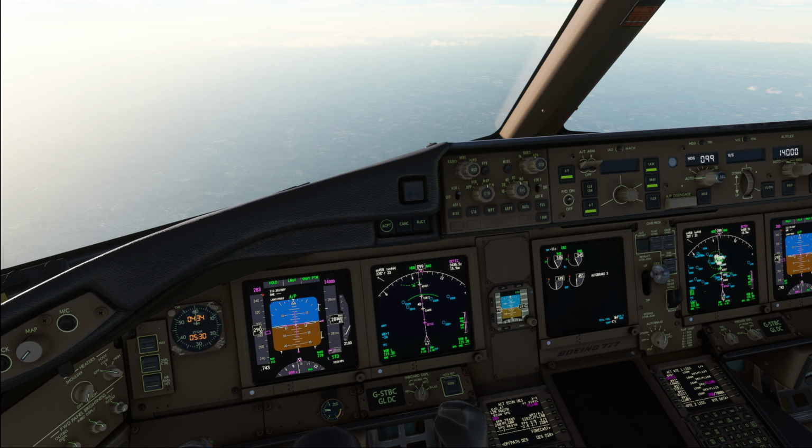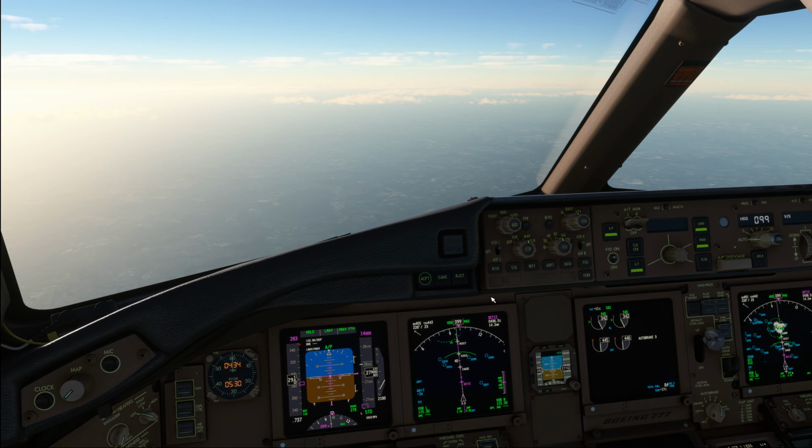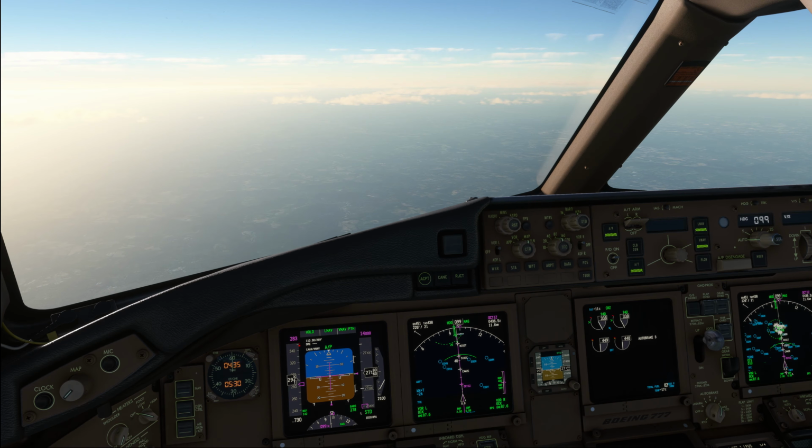To give you an idea of what the speed brake can do, there is a little table in the flight crew training manual of the 777. So let's have a look at a couple of default values in the descent. If the plane descends at a speed of Mach 0.84 or 310 knots, when passing flight level 200, we expect approximately 2,200 feet per minute rate of descent in idle thrust. Now, if the speed brake is used, those 2,200 feet a minute increase to 5,300 feet a minute. So that is a super effective speed brake.